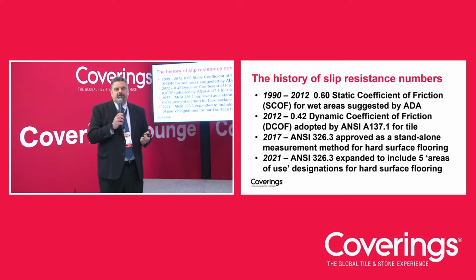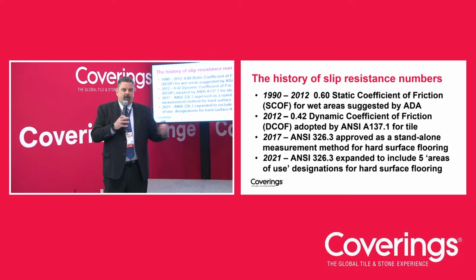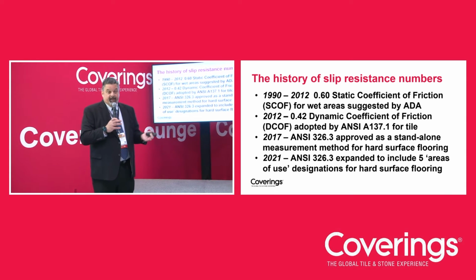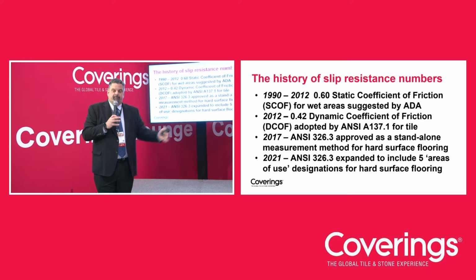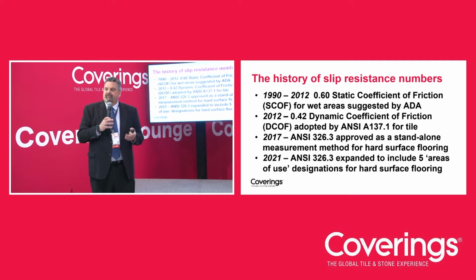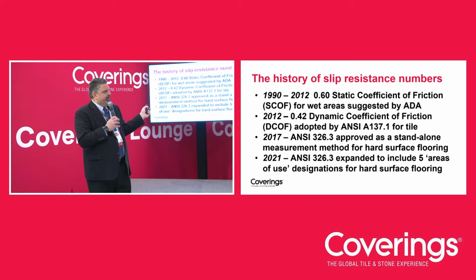So about 2012, the tile industry passed a new standard, and that's the dynamic coefficient of friction. It's a little different box, a little more elaborate, and it actually drives along the tile. It measures the resistance to movement over time. Each millisecond, it's measuring how much resistance there is to me driving over the surface of this tile. So the dynamic coefficient of friction is a moving measurement. And what we found is that a wet DCOF number of about 0.42 was more or less the same as that old 0.6 number.